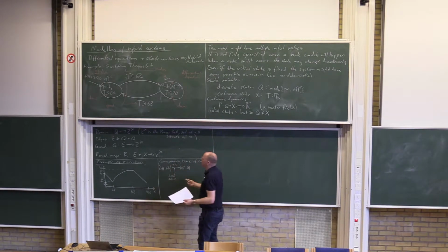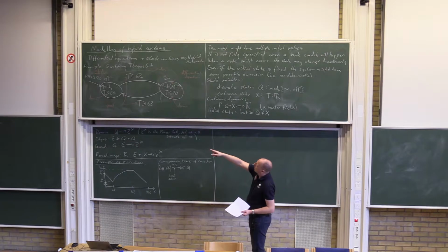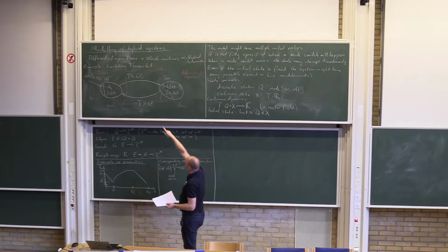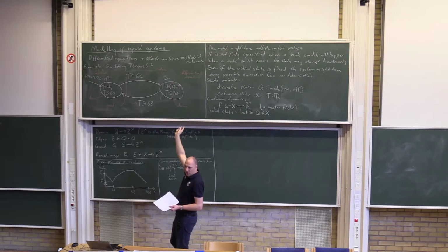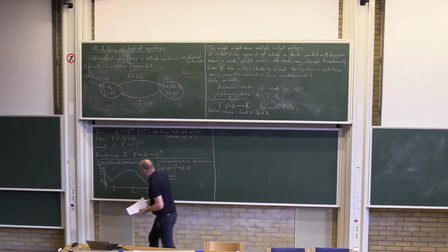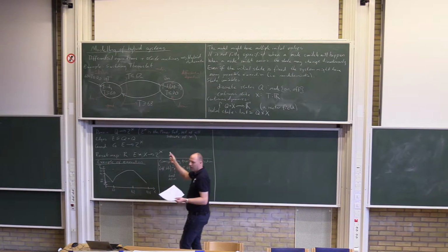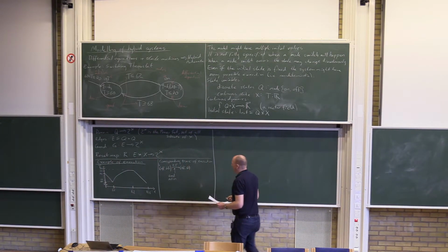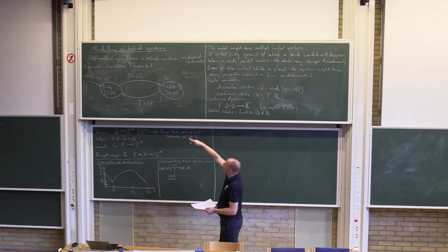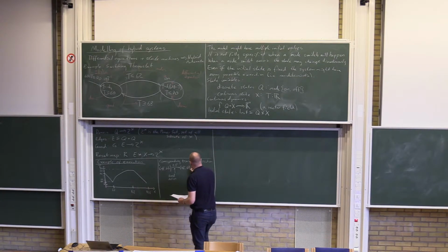Okay, and then what happens then? The guard condition is fulfilled, so a transition might happen, and in this case if we had 61 degrees and switched here, let's assume that was the case, then it will switch from off to on, right? So we will then go to on.